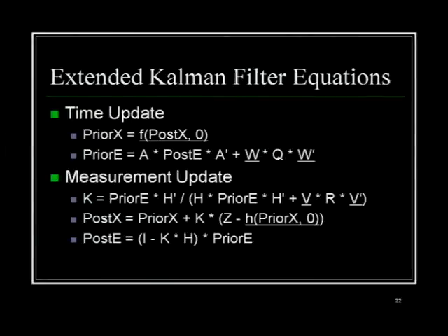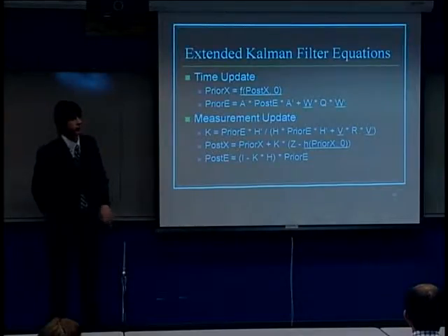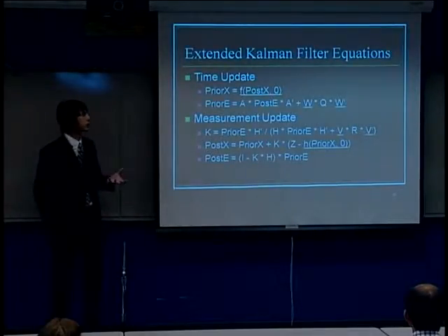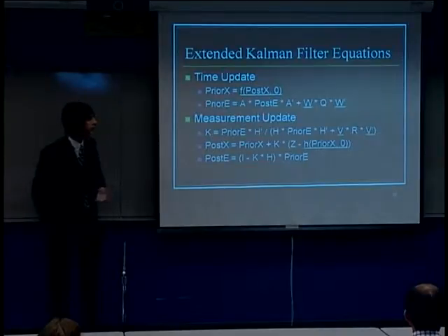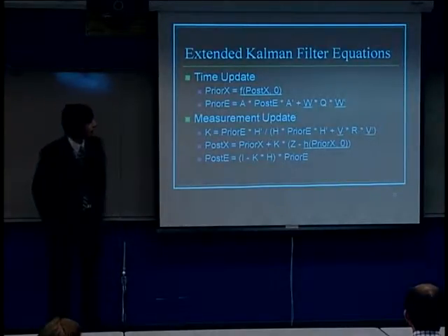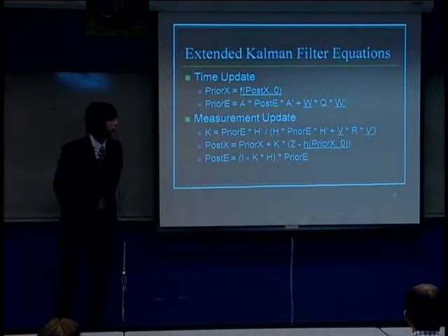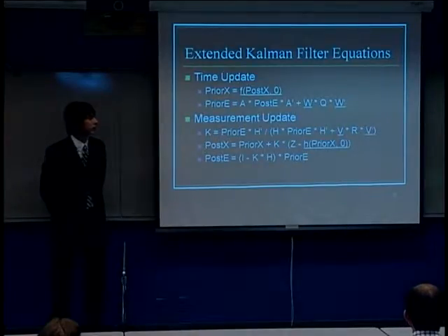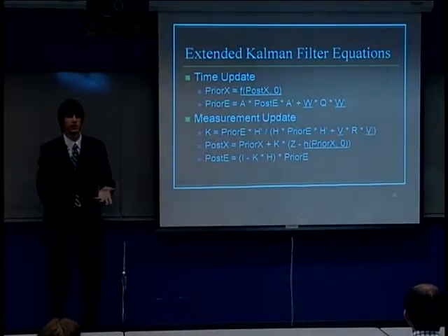So this is an example of what the difference is between the extended Kalman filter and the regular Kalman filter. I've highlighted the differences. Instead of using matrices, which you multiply by the previous data, you actually use functions which take the previous data and then use some sort of nonlinear calculation to update it. This is found in both F and H. And then you also have the two Jacobian matrices W and V, which are used to update the error and the Kalman gain, since you're updating these at every step and it's not linear.